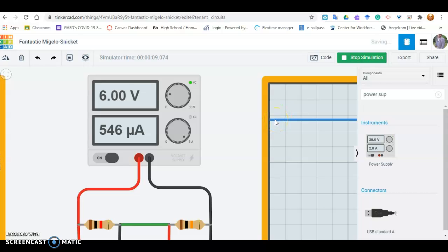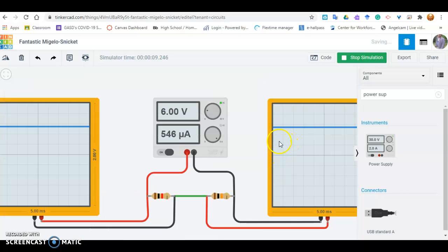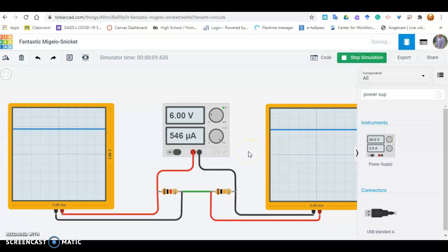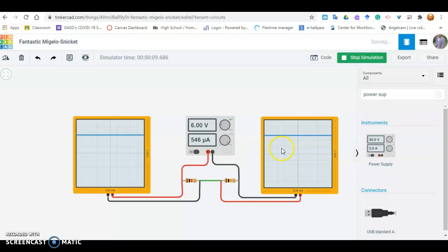And what you see above our horizontal is 2 volts, 4 volts, 5 volts, and 5.45 is about what this reading would be, again, if you calculate out the voltage drop difference. Notice the DC voltage on the oscilloscope appears as a straight line. It's a straight line.